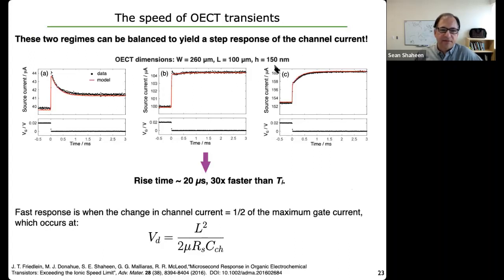So we dug into that a bit deeper and started to look at really modeling the different time dynamics inside the device, in particular looking at the different capacitances of drain, source, and gate, and what the field strength was at each one of those electrodes. And it turns out there's an intermediate case between the spike and recover and the asymptotic behavior, where those kind of balance out.